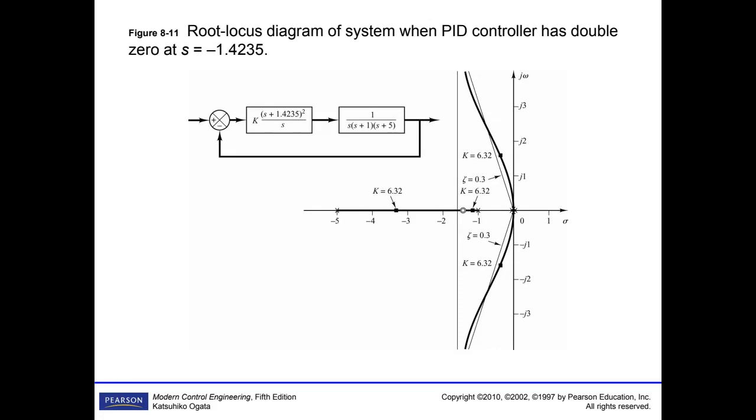Pole is moving in this direction, and we all know that the traveling of the poles ends at zeros. So with that double zero, poles are moving like this, and these have no effect at all. It's far away from origin. However, these two provide that kind of curve. Who is going to interpret that one? Are we happy with this curve?